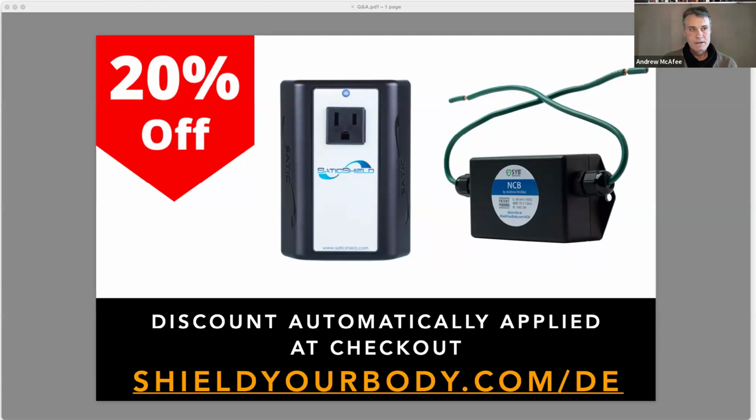Unfortunately, it's yes, because of your neutral. There are three wires we're talking about. The hot is what's turned off with your breaker. The neutral and the ground are never broken, opened, or cut off unless you do something other than what you already have. So the neutral is tied to all the other neutrals in the house. Any 120 volt appliance running in the home is touching all of the other neutrals always. The grounding conductor is touching the neutral at your main service.